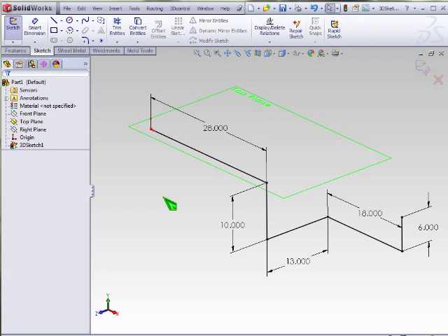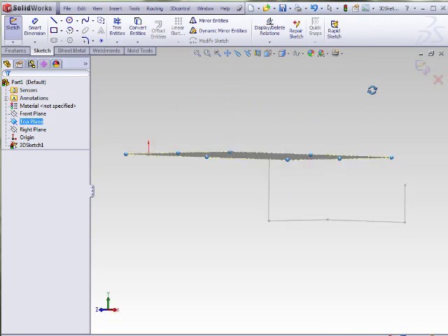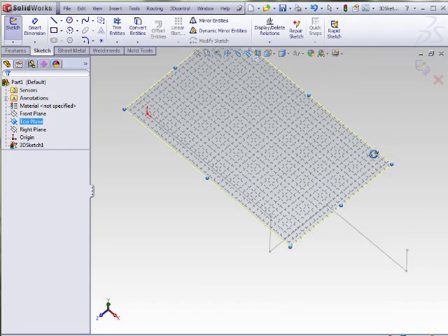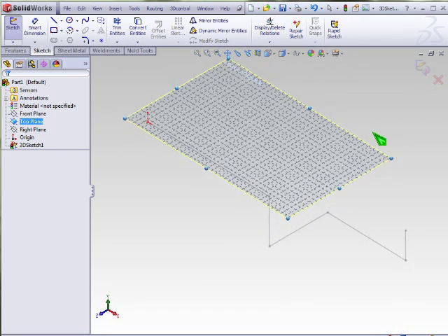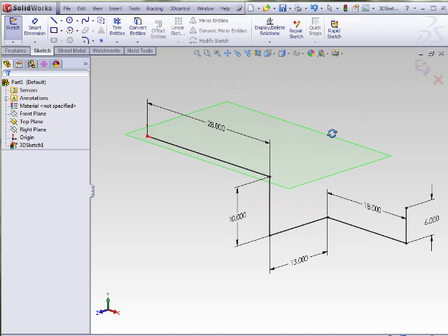Let me go ahead and double click on the top plane so you can see what happens. It turns into what looks like a grid almost, and that will show you that you are indeed temporarily sketching in 2D. Everything you sketch at this point will be locked on that plane. And once you're done and you want to remove focus from that plane, double click in the background somewhere and you'll be back in the full 3D orientation, if you will.